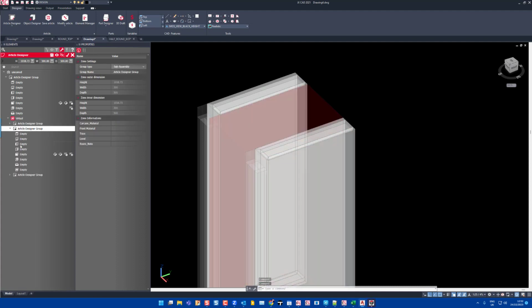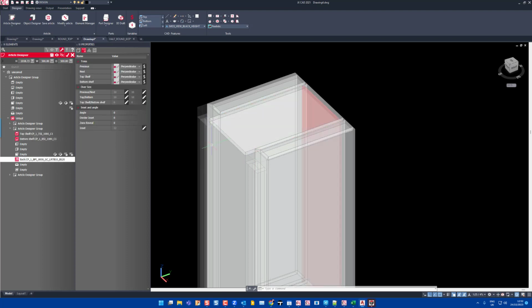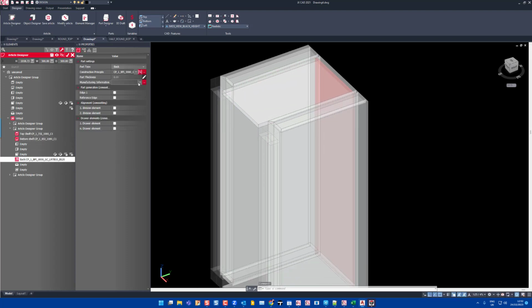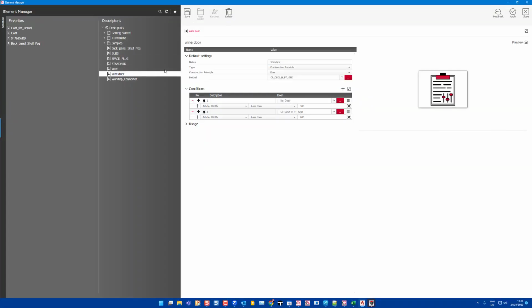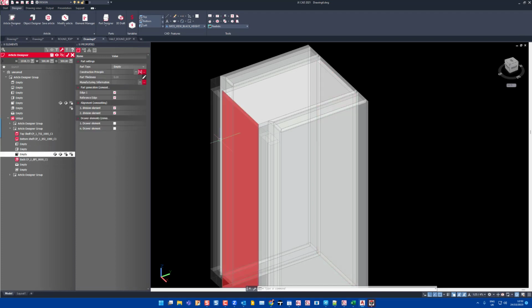And then in the center section in here we then need top, bottom and a back of some sort. We can then choose a different back. And in here we want to go to our zone and bring this in 100 mil. So we'll say that we want a zone inset of 100.